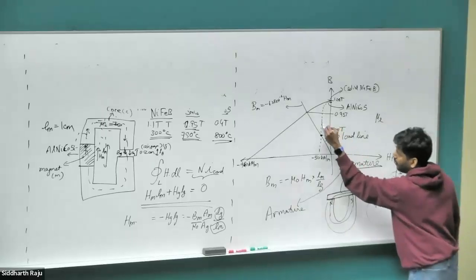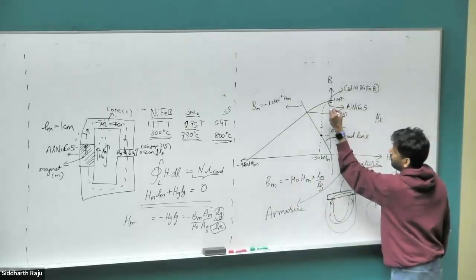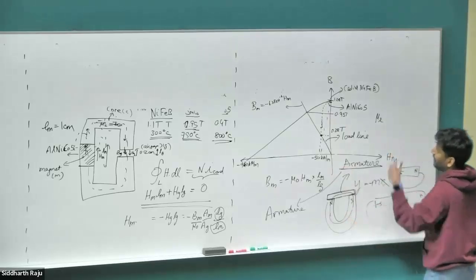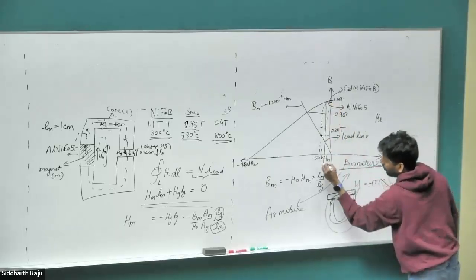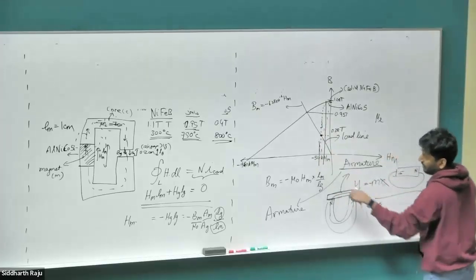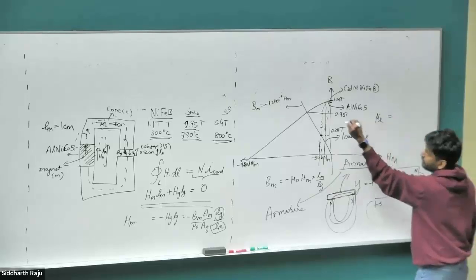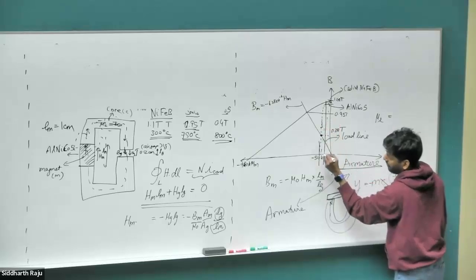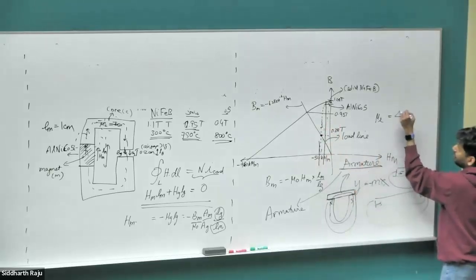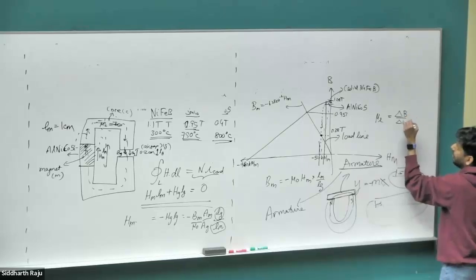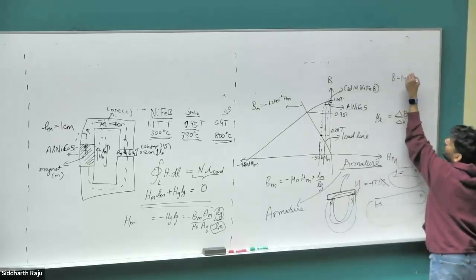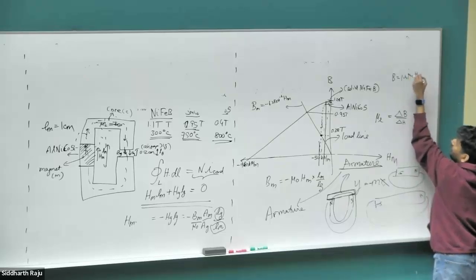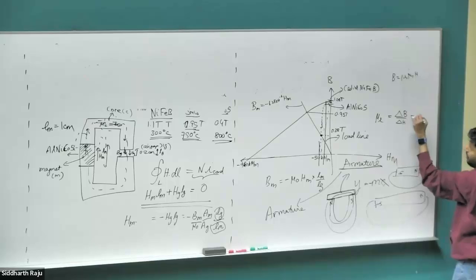Slope, perfect. If I look at the slope of this, let me assume for simplicity that it's somewhat linearly falling in this region. Over this portion where the magnet operates, it falls at quite a rapid pace. So if you take the difference between the B field here and here, whatever this value is minus 0, and the H field from here to here, that's delta B divided by delta H, because B equals mu naught mu r times H. So B by H gives me mu naught mu r, which comes out to roughly around 100 mu naught.